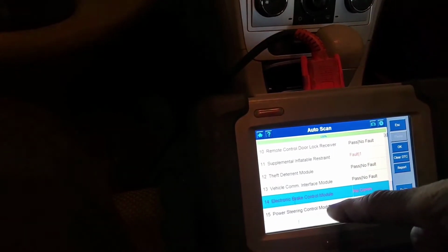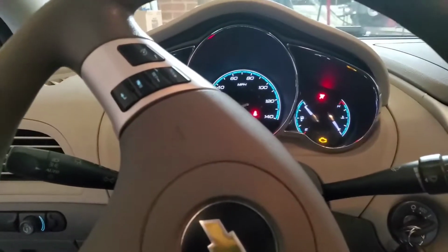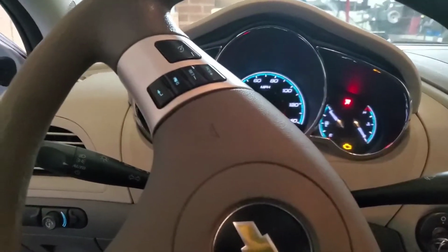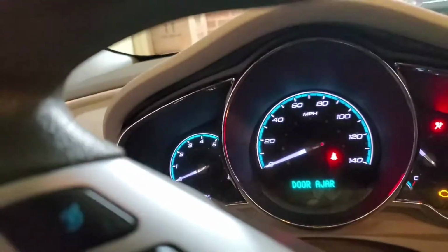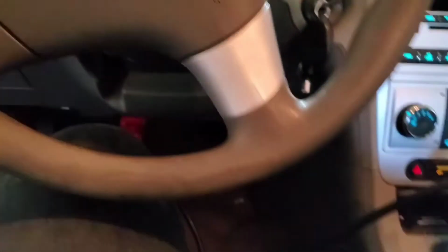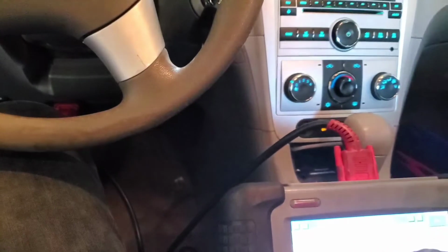Those codes mean losing contact with a bus or with other control modules. I'm not really sure if we're dealing with something different here, especially since the gauges started acting out. Even the security system module seemed to go on the fritz and wouldn't let the car start.